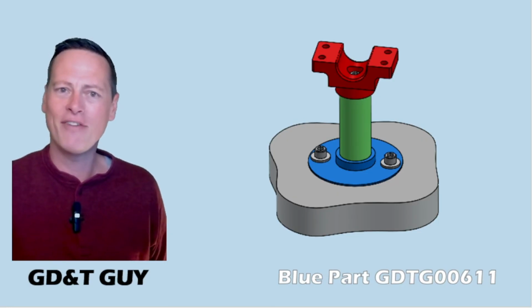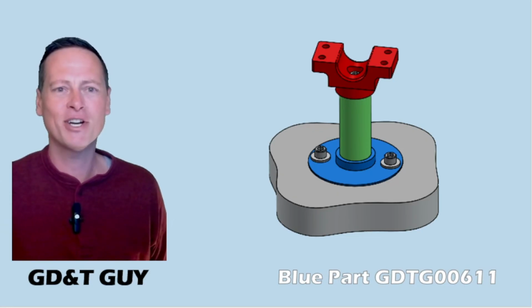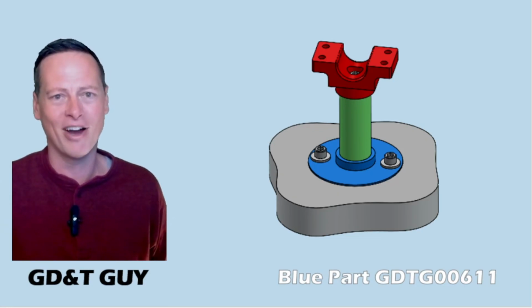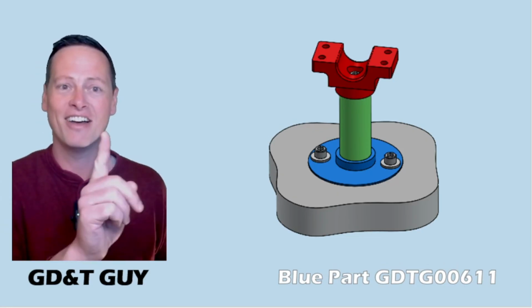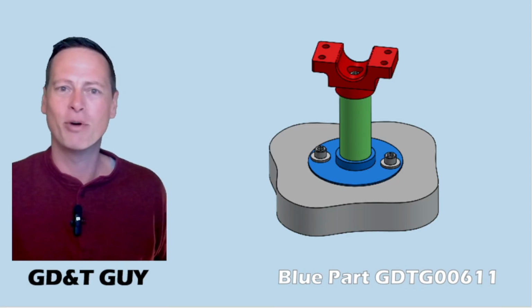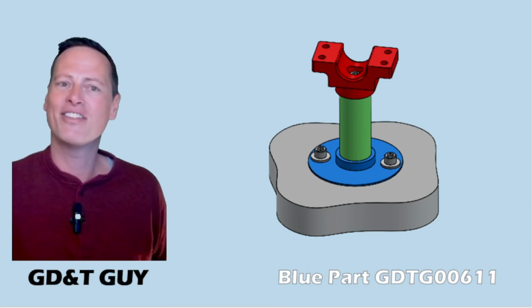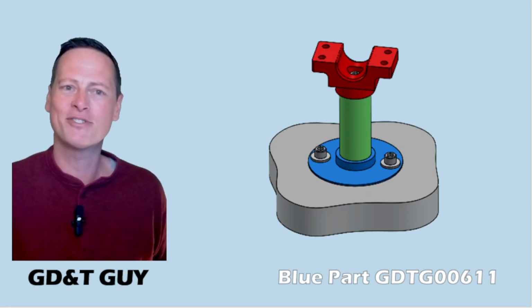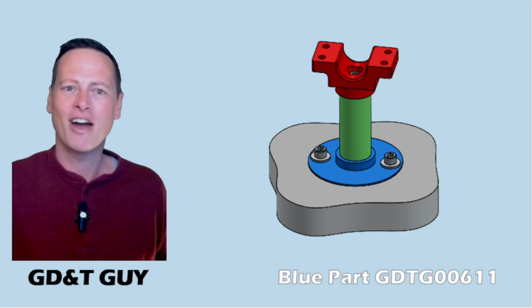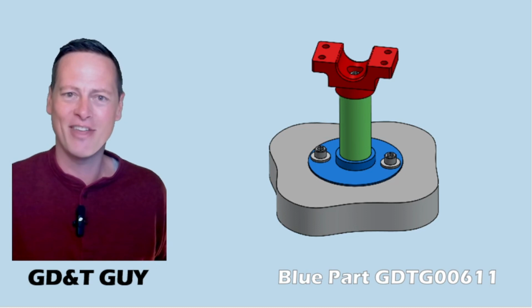But what we don't have anymore is an obvious tertiary datum feature in the blue part. Aha, a bunch of you will say. What about when we put the screws in? Then it's constrained on the screw clearances. Well, there's going to be a little sub-theme here that our screw holes and screws are better thought of not as locating features, okay? So stick around for that.